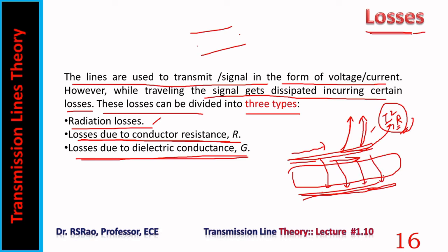These currents are called leakage currents, and these leakage currents are modeled by assuming a certain amount of conductance for the dielectric. It is supposed to be zero, but it is not zero, so we assume a small amount of conductivity for this dielectric. Now, while currents are flowing through the dielectric, here also a certain amount of heat gets generated.